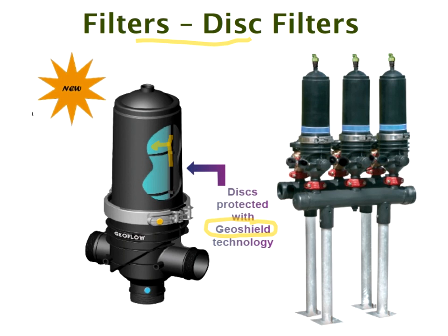And one of the tricks is you run the system and you get the stuff built up here, and a little bit gets squeezed in while it's running. And then as soon as you switch off, you open the flush here, just very quickly. So any goo that's on the outside will get, by reverse flow, it's not really cleaning the filter, but it will just get rid of this stuff here, will go around there, down and out. So you don't have this stuff lying on the outside here. Then anything that's trapped in between gets killed, and we've had, as I said, phenomenally good results.